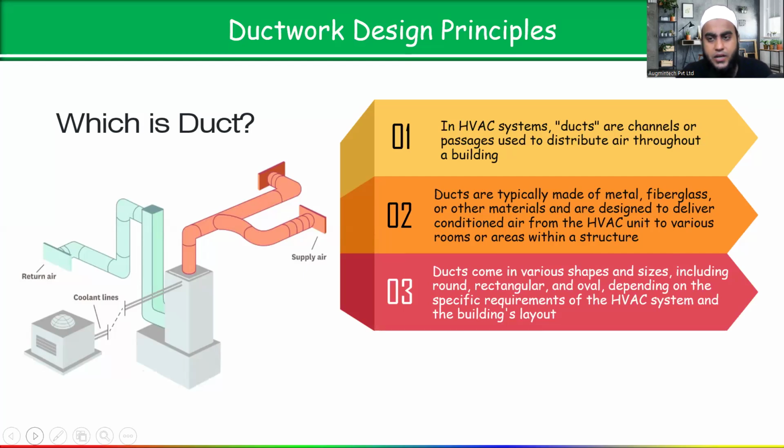But normally, you have seen, inside, which shape of duct are we using? Rectangle. What is the reason? Because inside, all of you know that the space availability is very important. We do not have that much space above the false ceiling I'm talking about. Generally, the architect will not give you that much space to run the services properly. So the height issue is very important inside. Always we have to face the height issue if you run HVAC or MEP services like firefighting pipes, plumbing, duct.